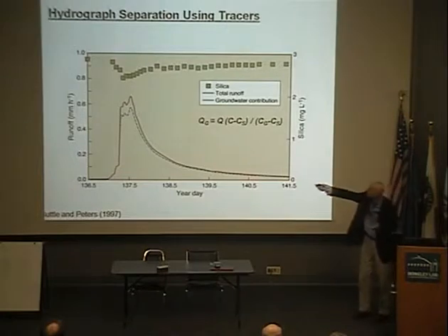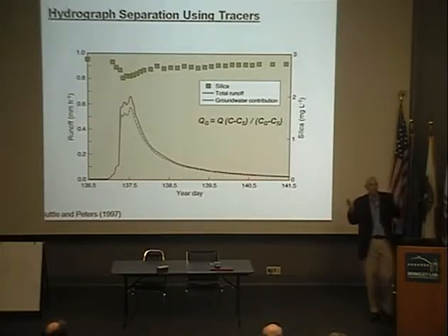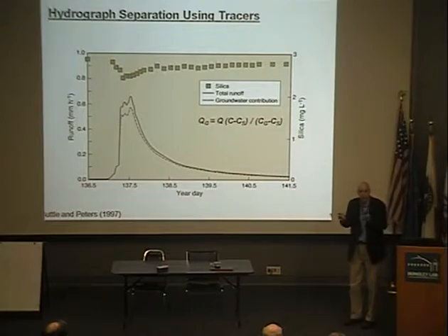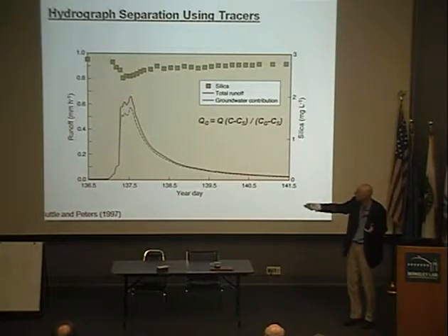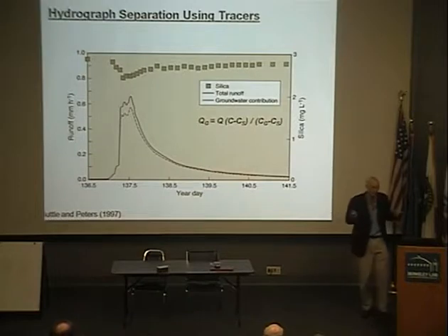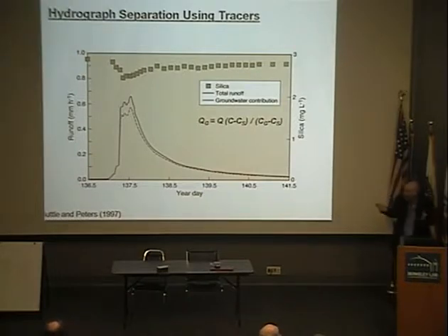The assumption here is that silica in runoff and rainfall is essentially zero, and all the silica is out of the groundwater. Since the silica concentration only dropped by about 10%, there can only be a 10% contribution of surface runoff during this flow event. On that basis, the authors calculated this is the groundwater contribution to flow within that upstream area.